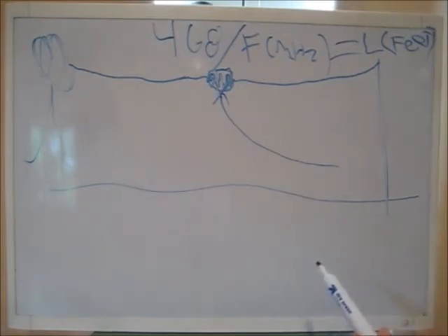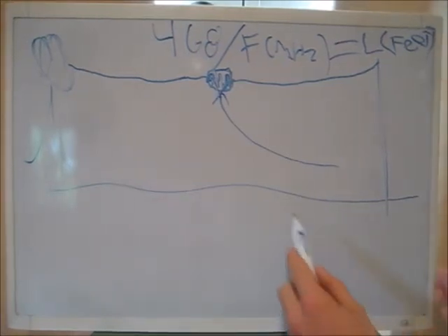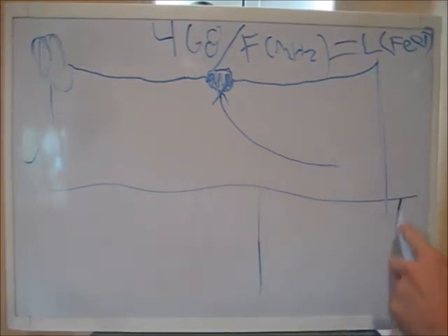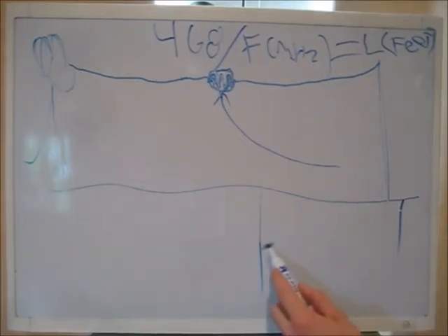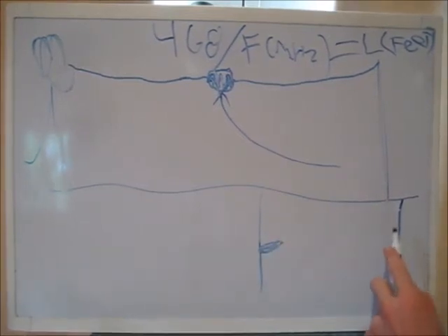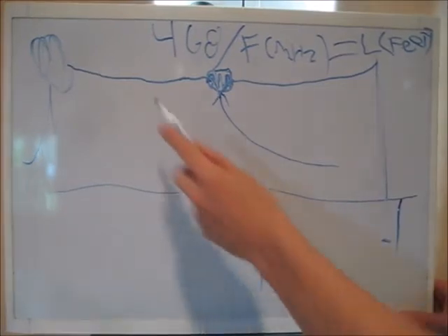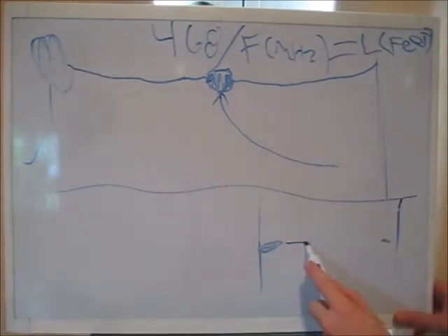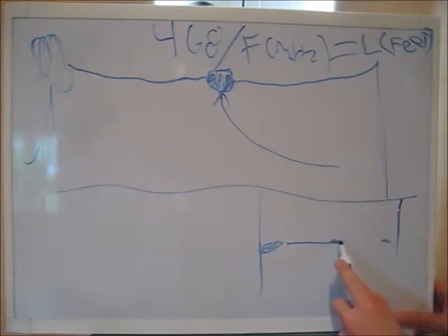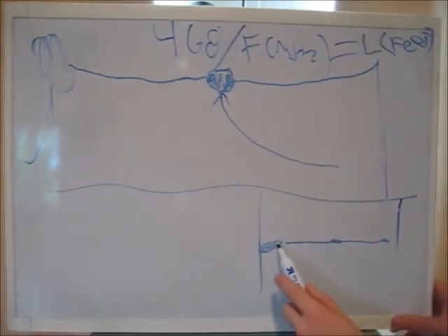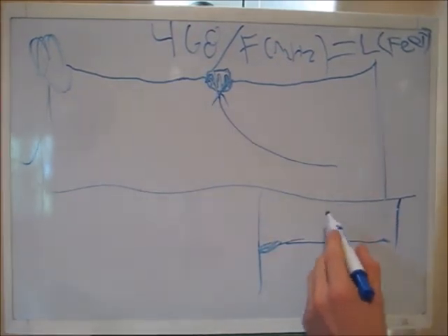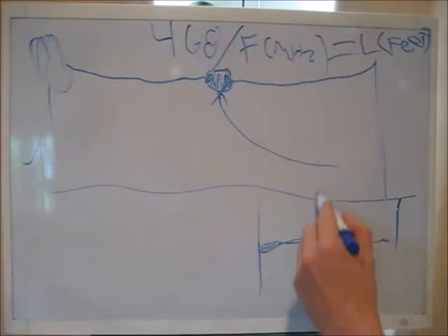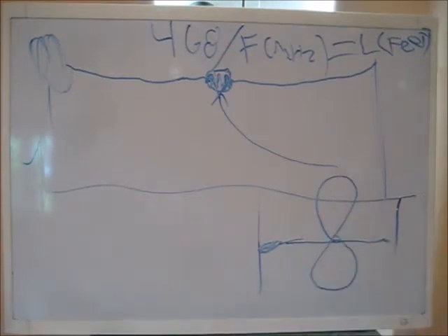That is a dipole. Now, down here, we're going to make a vertical view of this, okay? This is going to be a top view of this antenna. So, your tree is here, and your mast is right here, and these two pieces of wire, looking at it from the top, are running across here. You've got your center feed point, and then your other piece of wire tied off here and here. So this is how this radiates. It radiates looking sort of like this. Okay, that is the main way that a dipole radiates.